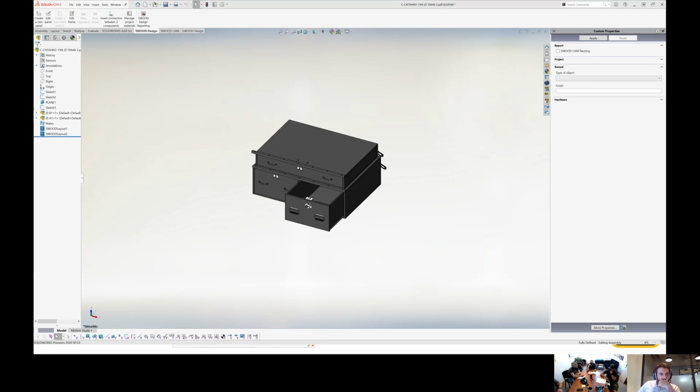What kind of things did you find to cover on what you cut out? What issues did you uncover when you cut the vaults out? It was rounding. One issue was the way this was set up, it was rounding diameters, so ours has to be specific. That was an easy fix though. We just compared the G codes. And then the other thing was a depth issue. When this outputs the G code, we have to add on our spoil board. We have a special SCM program that does that. And after that, it worked fine.